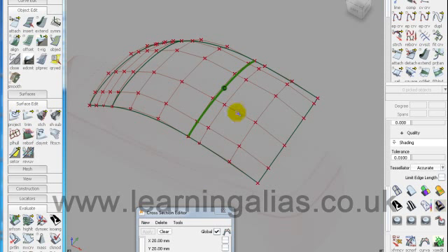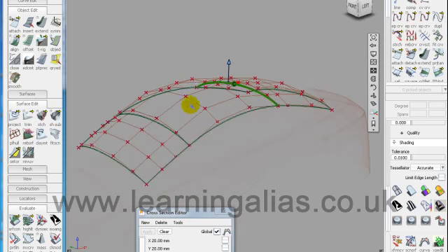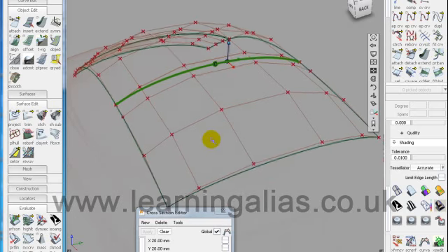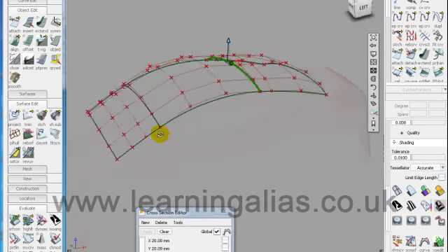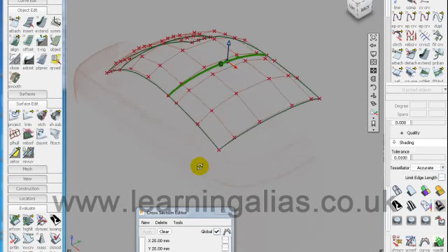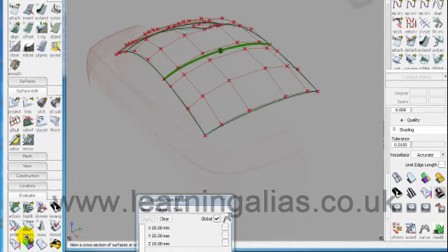I've just changed this degree to 5, but of course I could have done that when I built the rail surface. So actually I would advise that's a better way to do it. Here I have curvature now, and I'm fitting the mesh, which we'll check, and here we need to put in a blend. So it's just a question of how you go about building a surface, whether you need to put in a blend or not. If you put in a blend, you have a lot of control over the flow of the highlights.